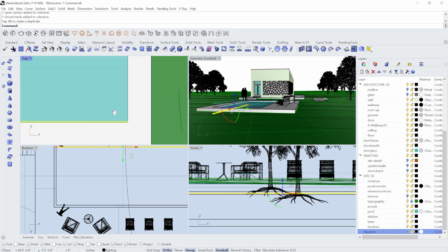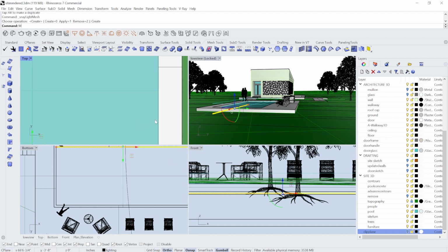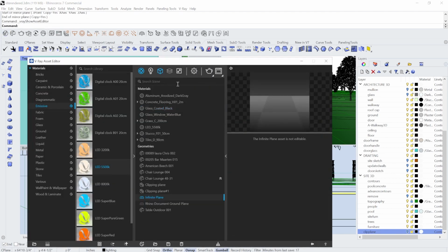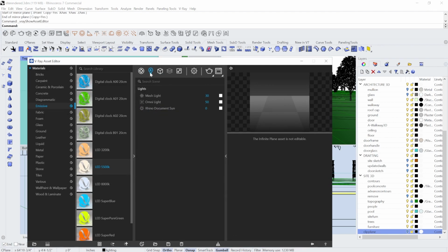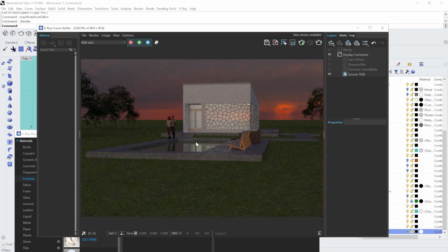And I'm going to now turn it into a V-Ray light by clicking on convert to mesh light. All right, so that already sets it up as a light. I'm going to mirror. So that actually is going to be the same object. You can now see it in my lighting command as mesh light, here. It says mesh light 30. And what we can do is come to our view again and render this.